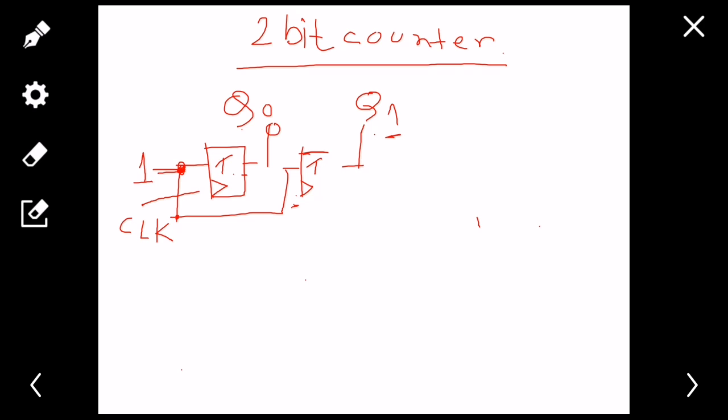So see that. This was my flip-flop again. Okay, so there you have it, you have a down counter. What I did is I just changed the type of the flip-flop. Previously I took a negative edge triggered flip-flop, now I'm taking a positive edge triggered flip-flop.